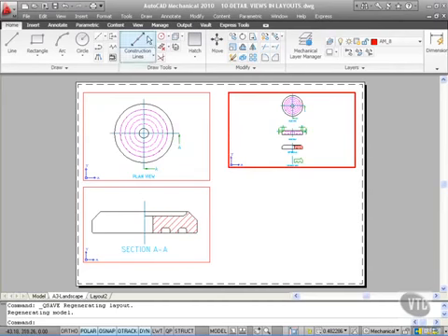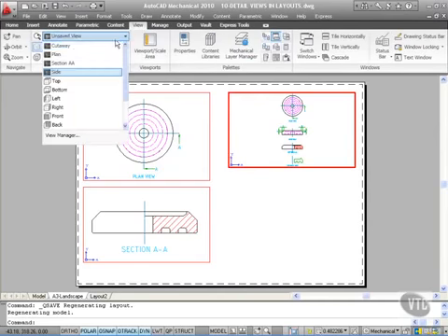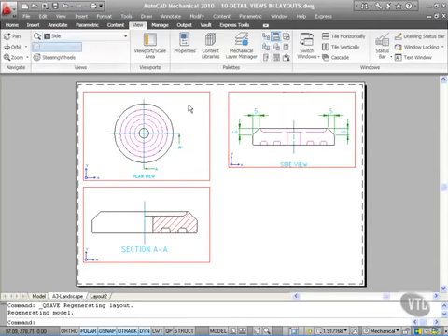So I go to the View tab here, and what I do quickly, I click on here, there's my named views at the top there. See model views with the black symbol there, and I want the side view, that one there. So I click, and it zooms to the side view. Now you'll see there, where I set up that named view, I can just see some bits of text there at the top. So I double click inside the viewport, like so, and I can pan.